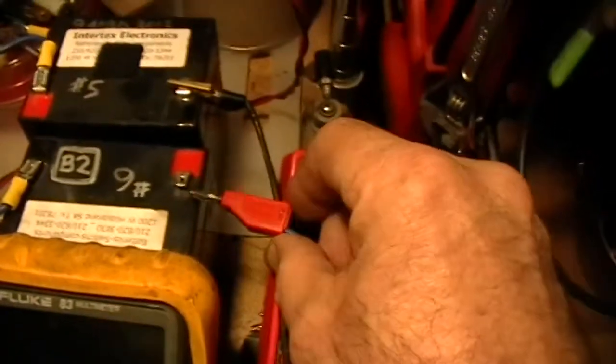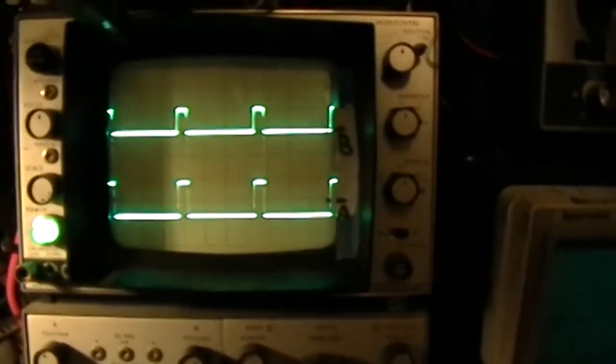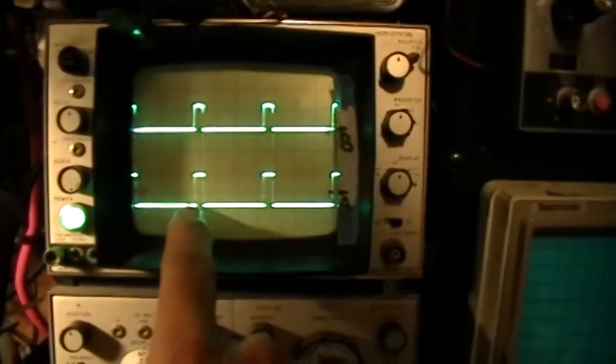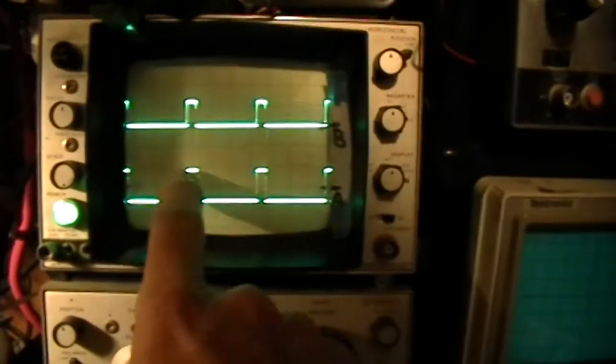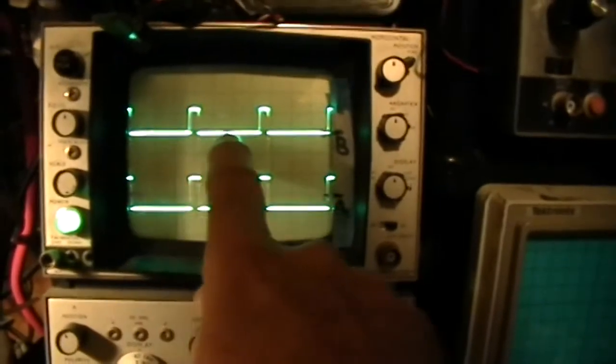So go ahead and hook up the 24 volts power to the circuit, and now I'm going to increase some amplitude here. By the way, we're not using any offset on the function generator yet. So I'm going to increase the amplitude, and now you see something going on here. This is current through the Q1 MOSFET. Remember, now we're giving the Q1 MOSFET a positive gate signal, and it's coming up. It came up higher now. It's up to 5 volts, and when that happens, the Q1 MOSFET turns on.